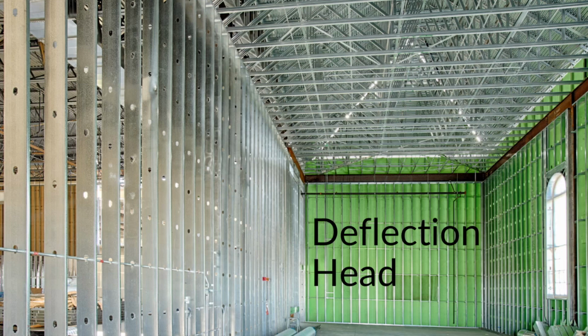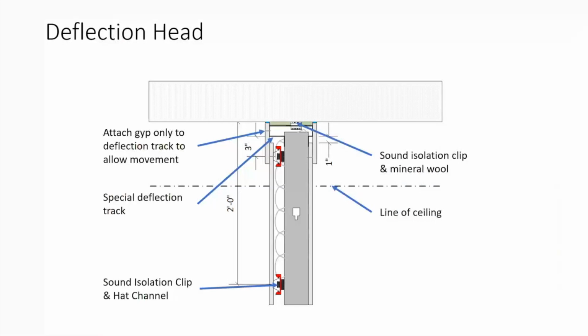All right, next bit here is a deflection head. And for those of you that are paying attention, you'll notice that the image I pulled here doesn't actually have a deflection head in it, but I just found something with steel studs that looked kind of cool. So forgive my non-applicable image. A deflection head, you find this a lot in concrete construction, where you may have some deflection movement in the structure for one reason or another, and you need to allow differential movement between a stud wall and the structure up above.